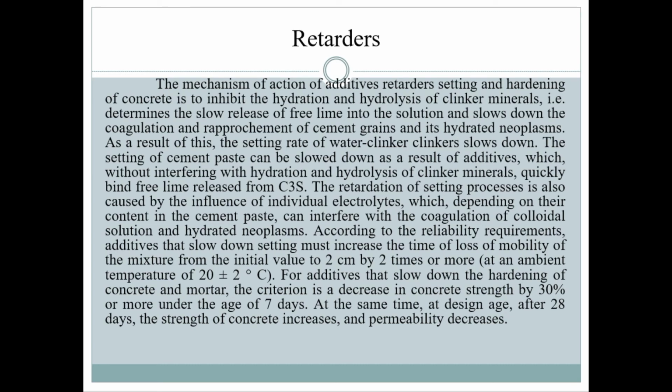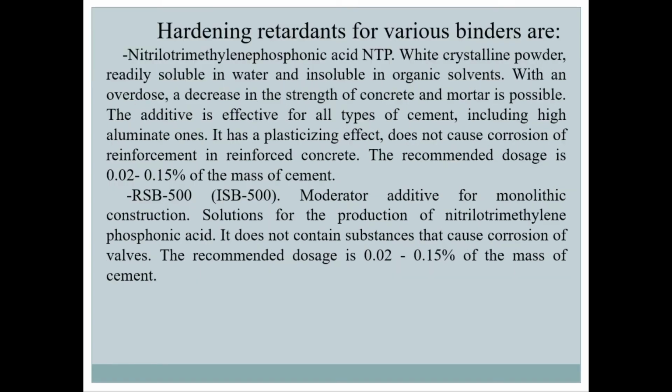For additives that slow down the hardening of concrete and mortar, the criterion is a decrease in concrete strength. Hardening retardants for various binders are nitrilotrimethylenephosphonic acid, NTP, white crystalline powders readily soluble in water and insoluble in organic solvents.